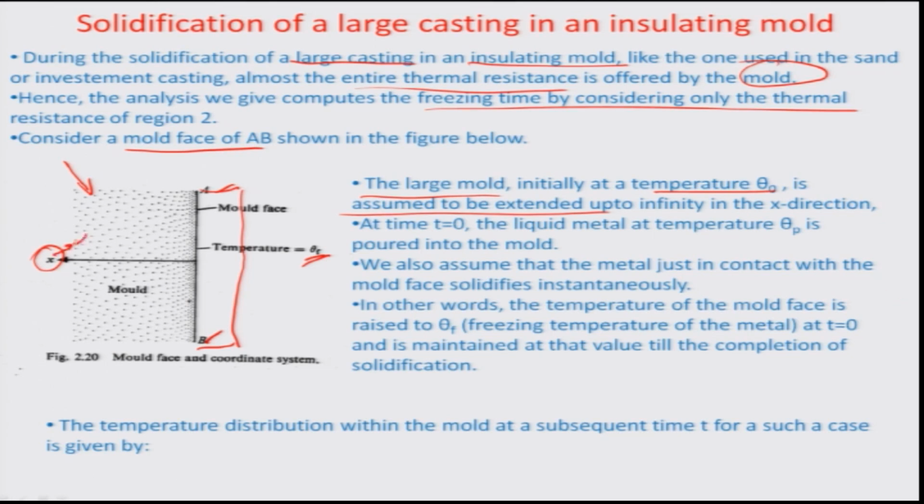So, extends to infinity, and at time t equal to 0 we assume the liquid metal to be at temperature theta p, and it has been poured into the mold. The moment it meets the face, it comes to the temperature theta f, which ensures that it starts to freeze, and then the solidification front moves ahead as a function of time, as a function of distance from the mold as well.